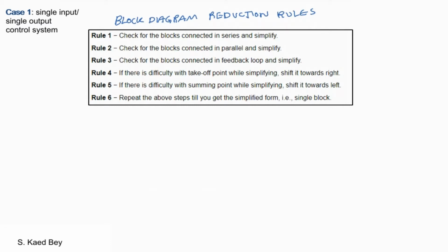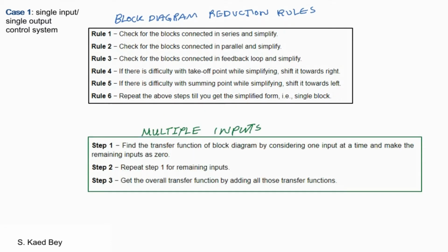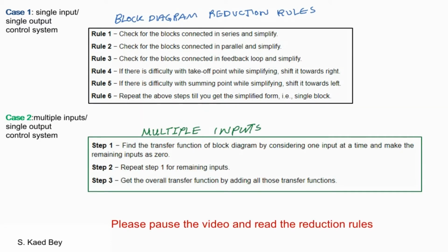This can be done by reducing the multiple subsystems into a single transfer function, hence the need for the block diagram reduction techniques. Please note that these block diagram manipulations shown here only work if the blocks in question represent linear operations, or your system can be represented entirely in the Z or the S Laplace domain.